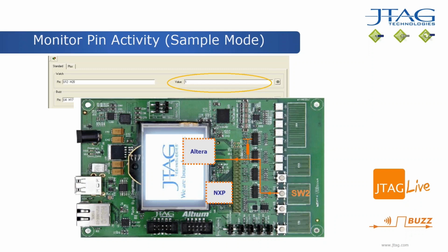Well, there is a mode of operation where it's not isolated, and that's called the sample preload mode. And we use that so we can set the board running in its normal operational way, and then use the boundary scan register to asynchronously sample an input pin and look at its value.